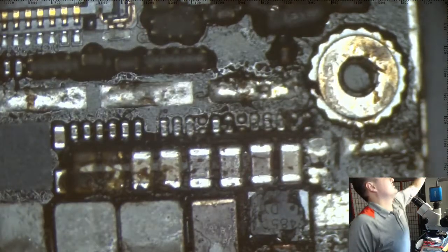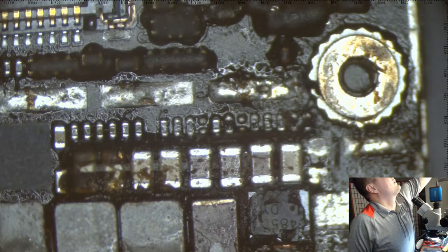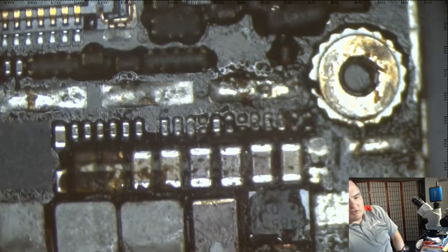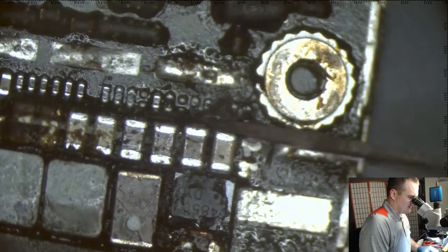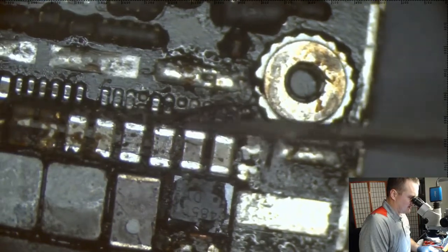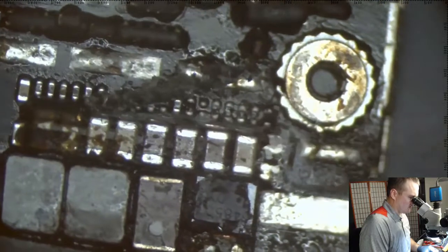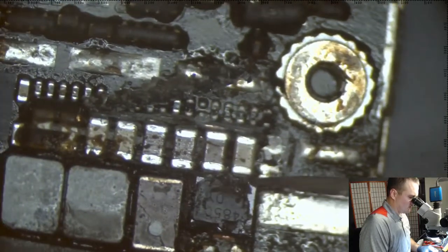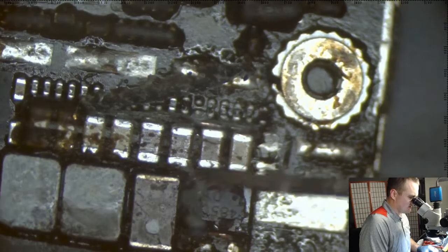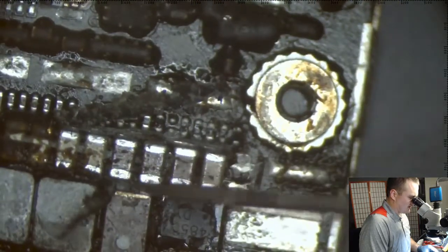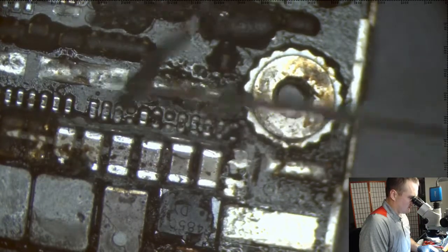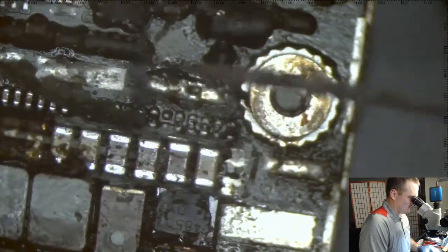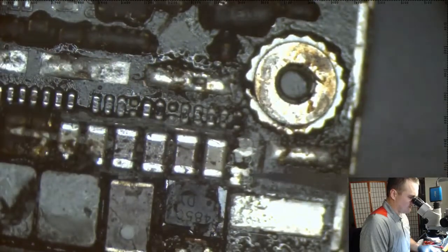But buy some iCloud locked boards. Get one that powers up and works perfectly, aside from the fact that you can't get past the iCloud lock. Save that one to do diode readings on, and then buy some more. Figure out what's wrong with them. Why are they no fixes? A lot of them, I bet you'll find, just have a shorted VCC main power rail. Great practice there. Do some short detection, voltage injection.